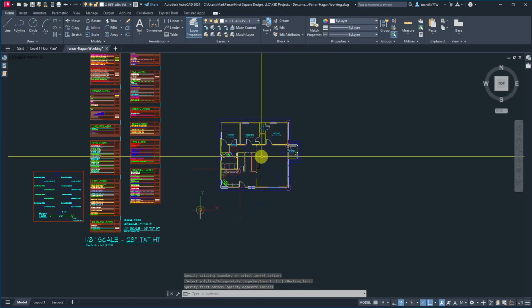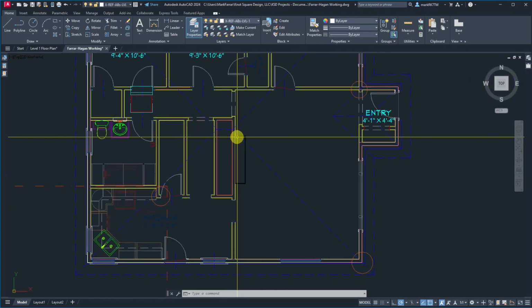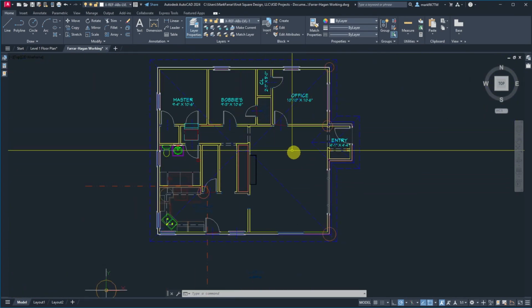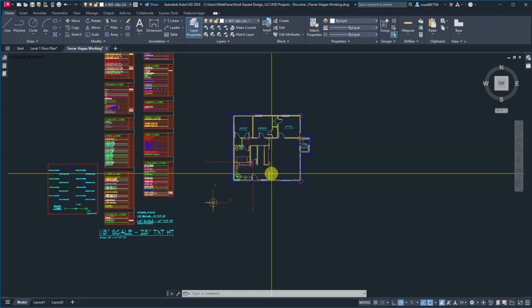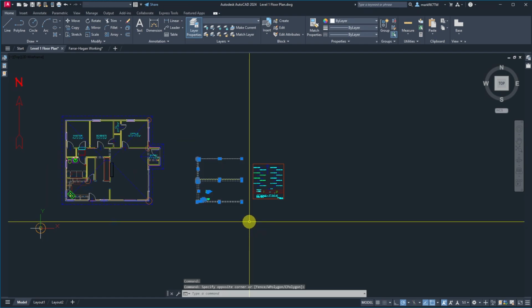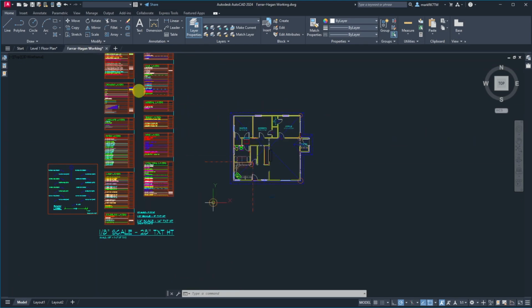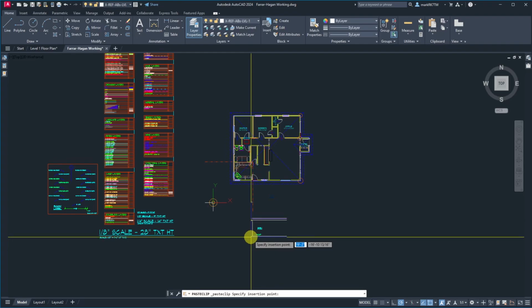And then when I copy it and rotate it around, I'll end up with all the other stuff that we need. There's a fireplace that's in there. We still got a little work, but this is an XREF now, so it doesn't matter. So what I can do is go to this plan, grab this guy, Control-Shift-C, and just grab a point, and then bring it over, Control-V, and that's my paint room.